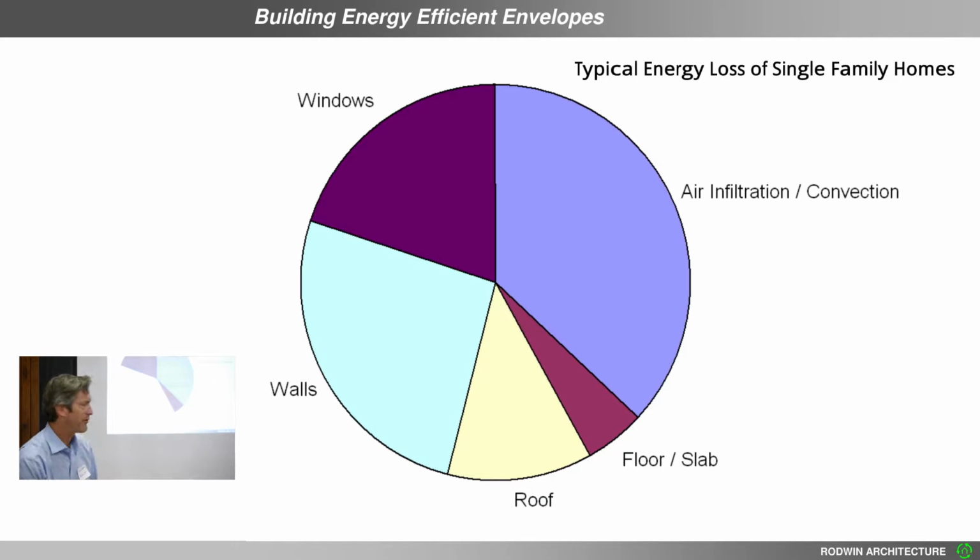Walls, this is insulation in the walls, so you can simply add more insulation. Lots of houses have really poor insulation. If you have fiberglass bats in your walls and you have 2x4 walls, I guarantee you have places in your walls where there is no insulation at all. Even if the builder said, oh, we put the insulation everywhere, there are pipes and electrical conduit, and there's blocking in the walls, and it takes up the space of insulation.